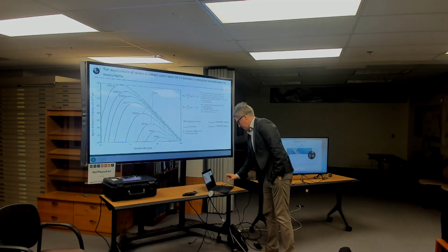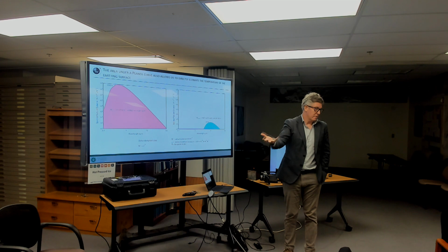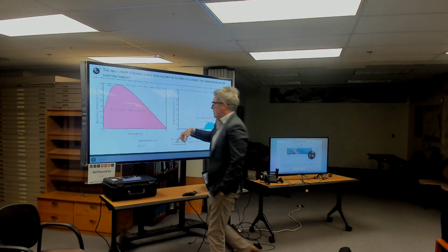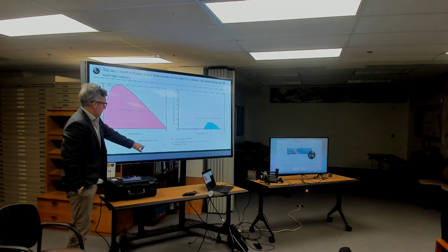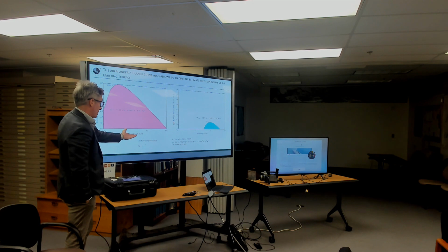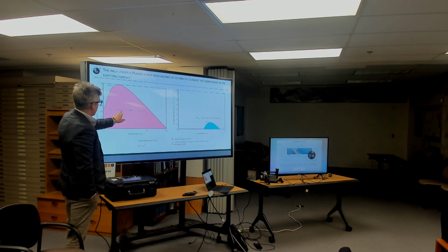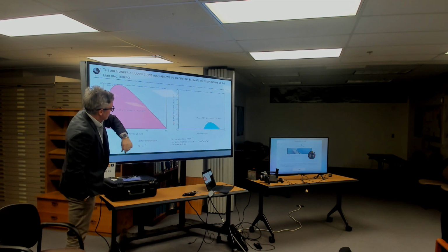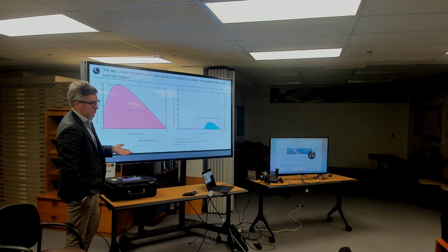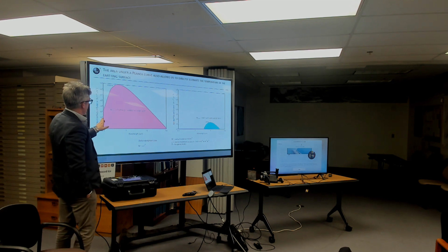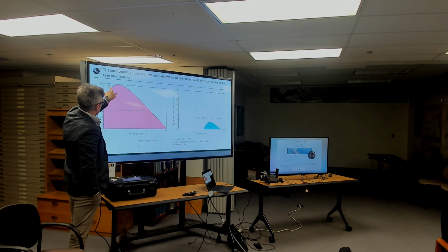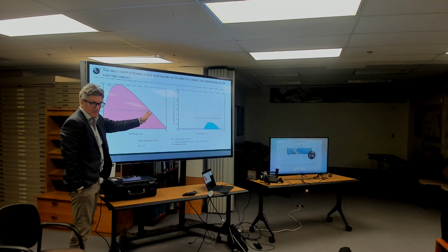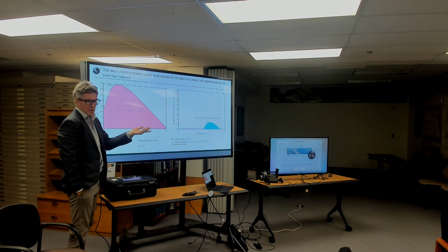Similarly, Stefan's law offers us a route to working out the temperature of a surface without touching it. So Stefan's law is the integral, just the area under the curve. Right? So here, this is the Boltzmann law, sigma T to the 4th, where sigma is a constant and T is temperature. For the sun, it's the constant multiplied by 6,000 raised to the power 4. For the Earth, we're raising 300 to the 4 rather than 6,000 to the 4, so it's a much smaller number. But the point is, the area under the curve is different for a 6,000 K emitter than it is for a 300 K emitter, and different again for a 350 K emitter. So if we knew this area, we could just invert it to work out the temperature.